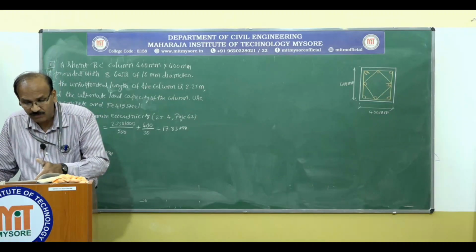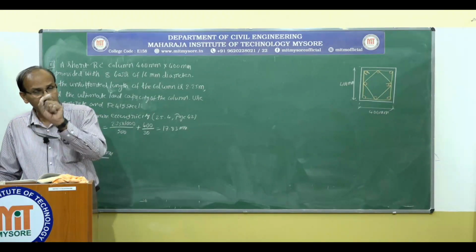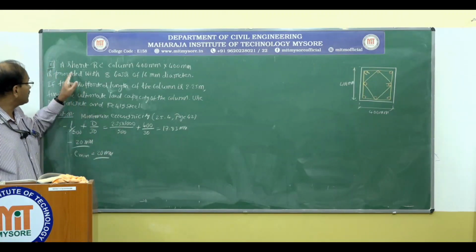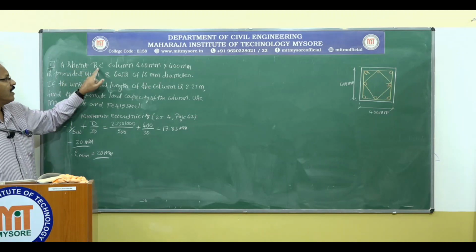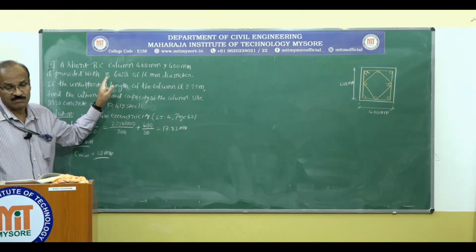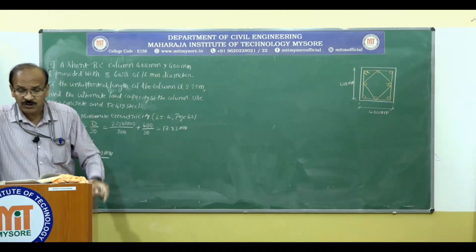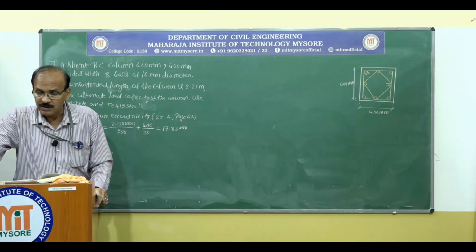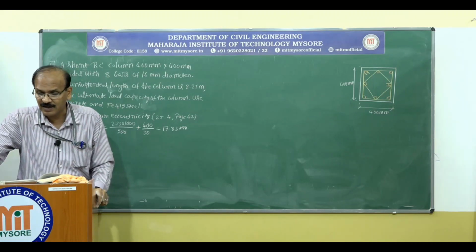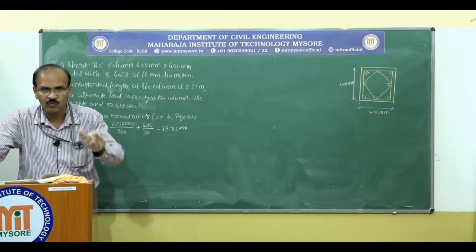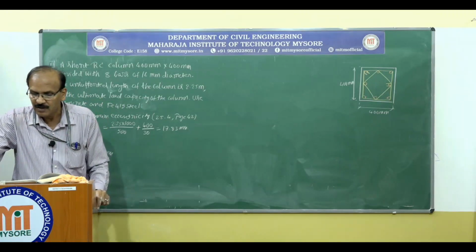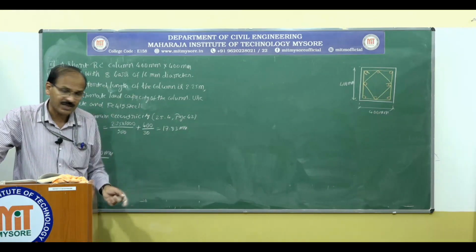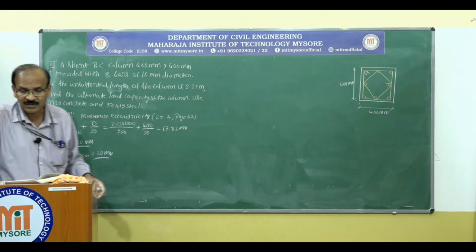So whatever the formula given under this is for a short column. We are dealing with a short column because the problem itself says it is a short column. Then it goes in this sentence: the member shall be designed by considering the assumptions given in 39.1, you don't worry about it, and the minimum eccentricity. Minimum eccentricity we have checked, that is 20 millimeter eccentricity.